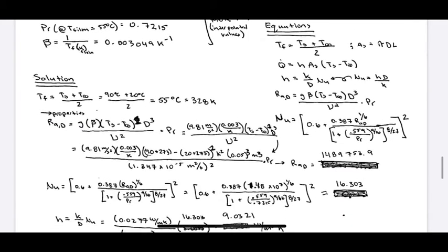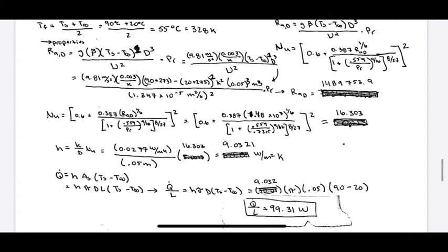Properties at the temperature of the film, which is calculated below, were generated. After writing down equations, everything was plugged in and solved for using the properties, as well as various equations, such as Rayleigh's number instead of Reynolds number to make sure the rate was okay, as well as Nusselt's number, which was then used to calculate the heat transfer coefficient of the average of the pipe.